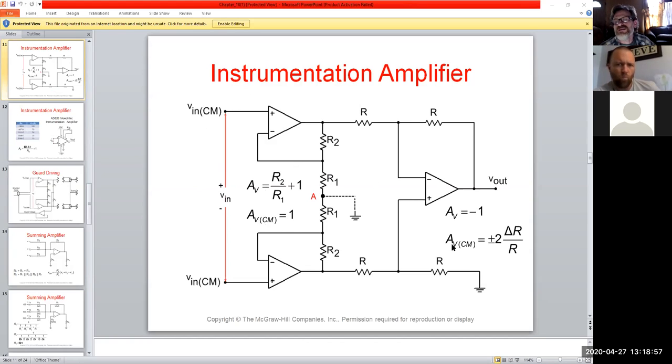And then that would feed into, and why would they do that? Well, the name itself, an instrumentation amplifier. So we're getting our voltages in, and if they had any degree of noise to them or anything like that, we would basically be using this whole beginning part here to reject any kind of noise or feedback, and feeding in nice crystal signals into this guy. Okay, and he's the one that's actually going to be doing the work here.